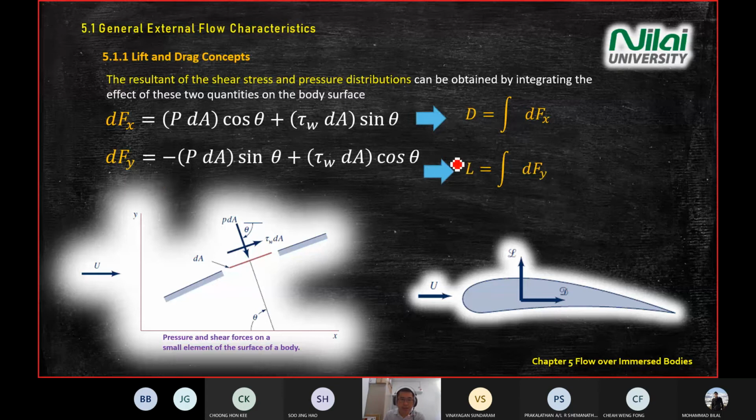Then another definition, for lift: we know that our lift is always perpendicular to our upstream. In this case it is along the y-axis and is pointing up. So L represents lift, equal to the integration of dFy. Later on I will not repeat all these lengthy equations. So when you see dFx, it means this whole thing, and dFy means this whole thing, and you integrate.